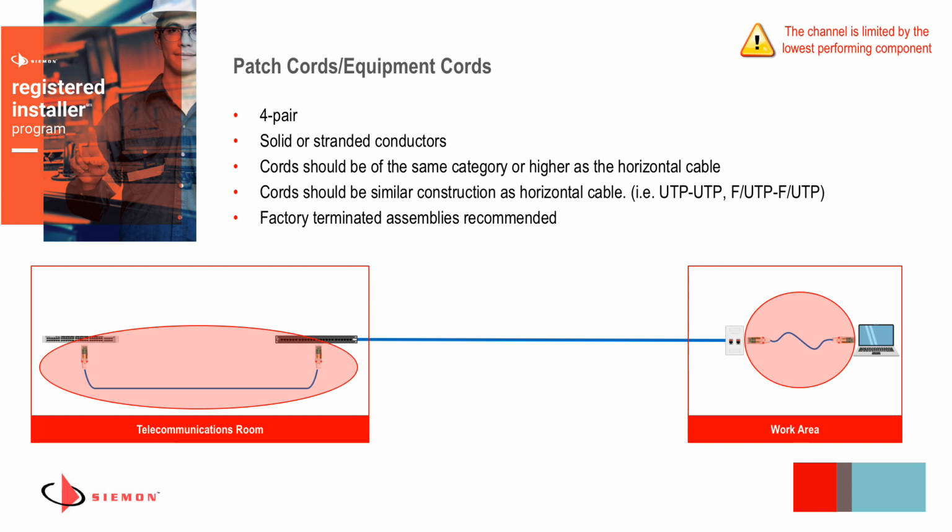And patch cords are not something that's readily constructed in the field consistently. Even with some of the higher grades like Z plugs, certainly have the ability to support that, but that makes for a very expensive patch cord. But certainly would be potentially an option. But as a rule, the cords should be factory terminated, and you have the benefit of having them pre-tested in lots of different colors without having to carry all that inventory on there. So let's move on to the next slide.